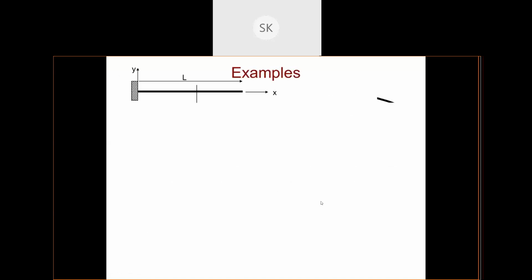So now let's take an example. There is a cantilever beam given to you, and the load is applied at the free end. Okay, so this is the moment equation. What is the moment equation? If you go back to your previous class, the shear force and bending moment diagram, what we do is find a shear force equation and a moment equation, right? So this is the moment equation. See, suppose this is my beam. I'm applying a load at this end. I'm taking a section at x.